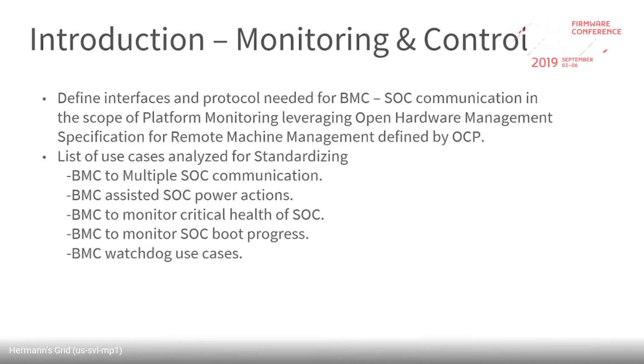For this, there are different compliance levels which support IPMI, and we also plan to support an MCTP PLDM based mechanism to manage not just the numeric sensors, but also the state sensors like firmware progress report codes, similar to post codes.